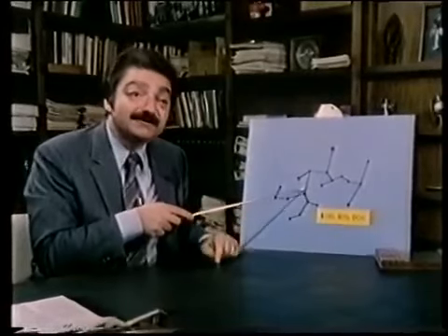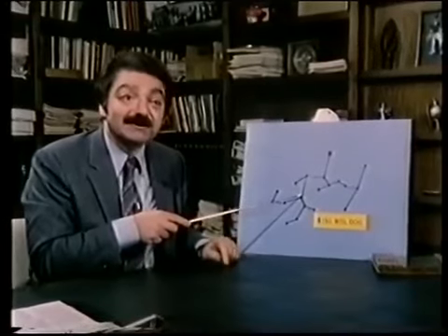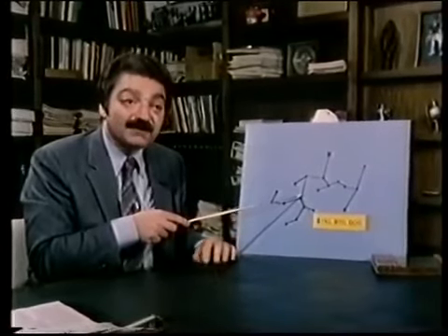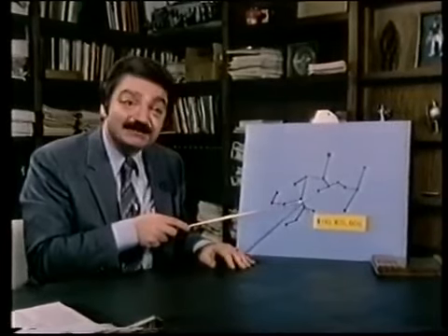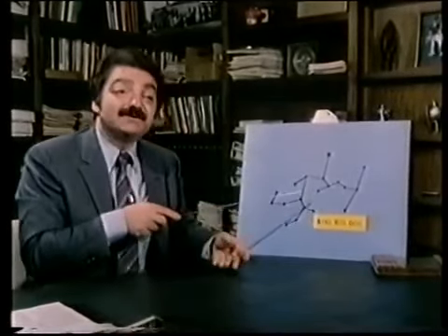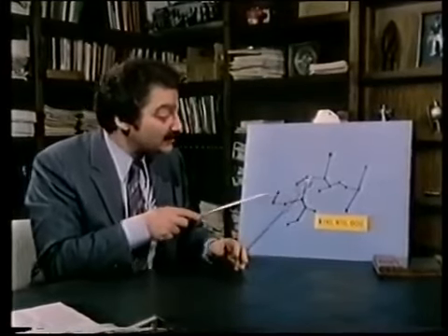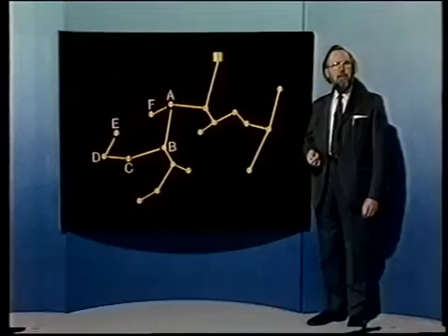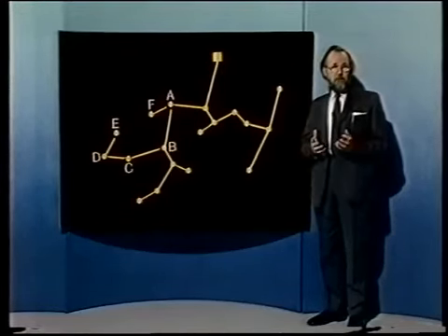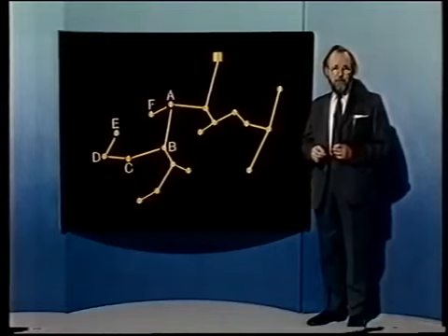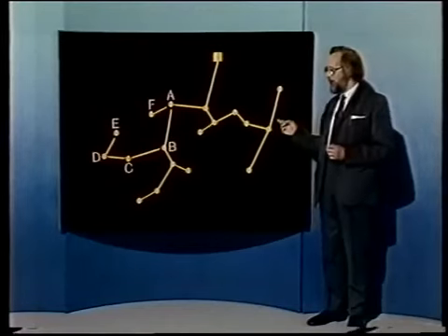I would then apply the first process, the optimization process for diameters of pipelines, to see what the cost of the network would be. If the cost of the network was lower, then I would accept that as a potential change, and I would start the entire process again. If the cost of the network were higher, then I would reject that as a change. Now this process of the delta change is so central to the solution that I'd like to illustrate it in a bit more detail. Well, let me show you how it works in general by looking at the next stage.